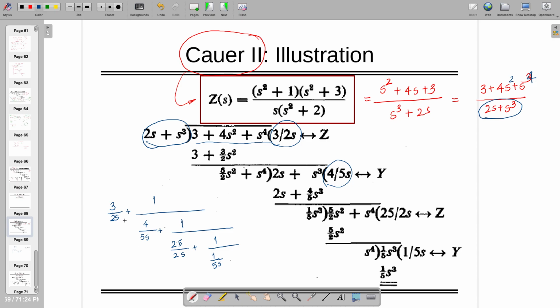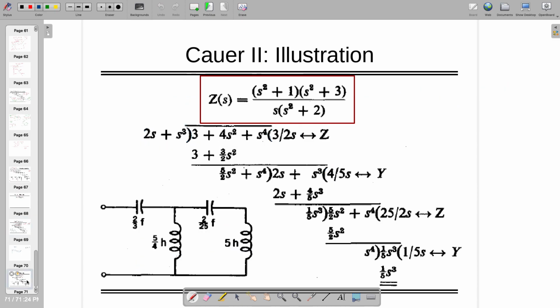So now all these Laplace operators are in the denominator. They are not in the numerator. So the first entry will be capacitor or inductor. Capacitor or inductor. This is capacitor. Second entry, is it capacitor or inductor? Inductor. And similarly here, this will be capacitor and this will be inductor. Right? So when you are going to draw the circuit it will look like this one, where you have to keep all these units in series.